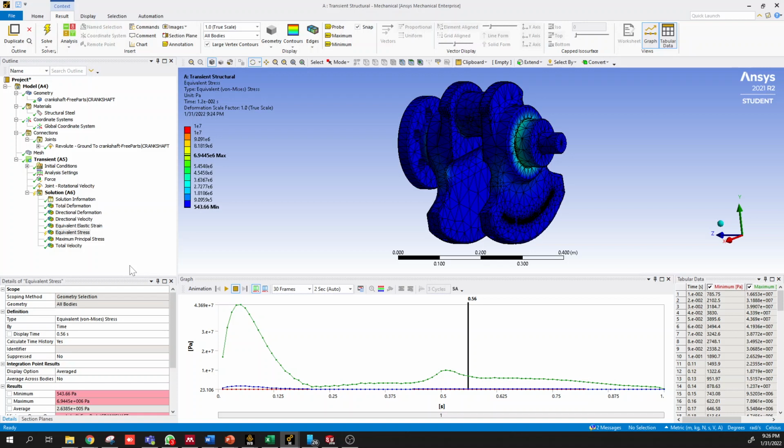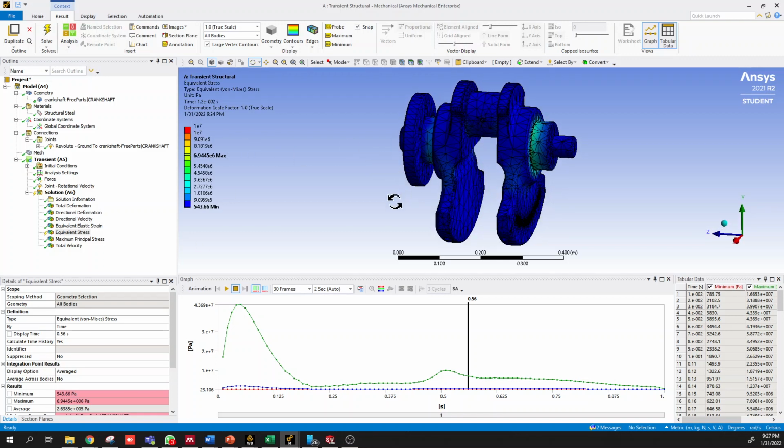The second thing to keep in mind is that often the load case development in these transient simulations, and understanding those analysis inputs, takes much expertise and many hours, if not months or years of someone's career, to fully understand where these load cases are coming from. And often that's more important than performing the analysis setup itself, because having good input data is the key to replicating reality and simulating the physical phenomenon that you're trying to look at.